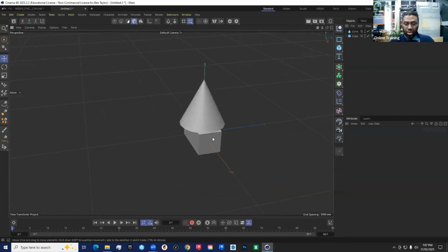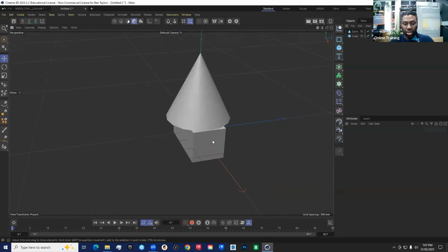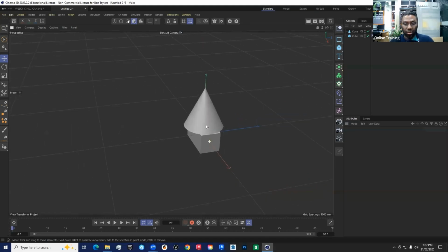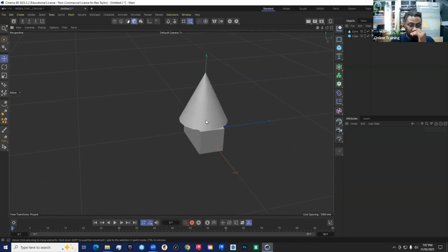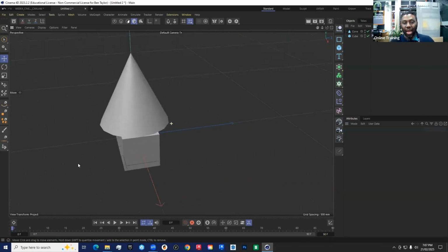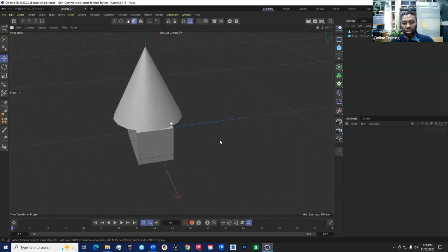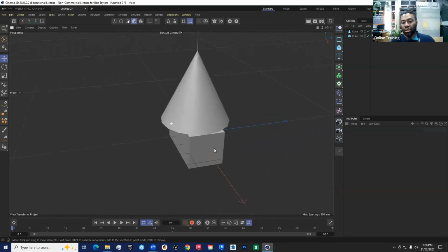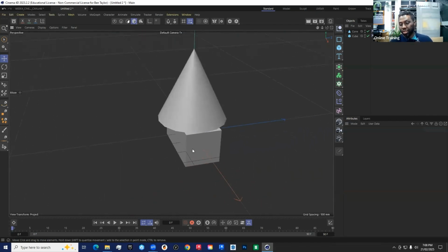We were using the circle to zoom in and out. You can also do that by holding down number 2 and clicking and moving your mouse. That should allow you to zoom in and out. And then the last one is number 1. If you hold down 1, you can basically pan and move things from side to side. So between those 3 buttons, you have a kind of dexterity. I'll keep mentioning them as we move around and do different things.